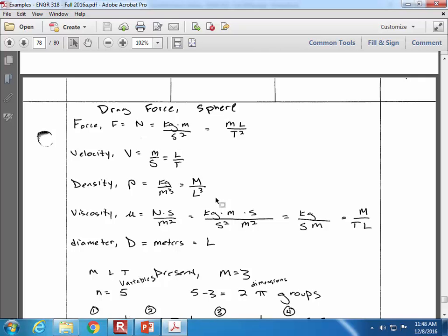here I've got the density times diameter cubed with units of mass. I'm going to use this as a tool to try and cancel out mass in other places. So if I do, for example, force, density, diameter to the fourth, then that's just going to have units of 1 divided by t squared.